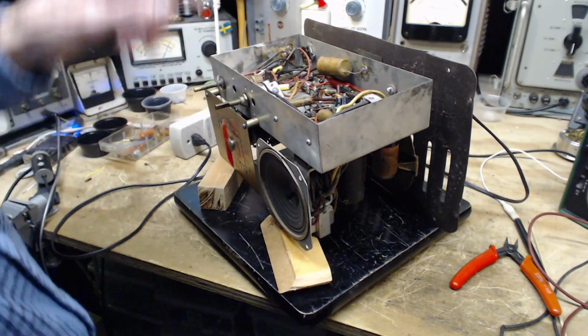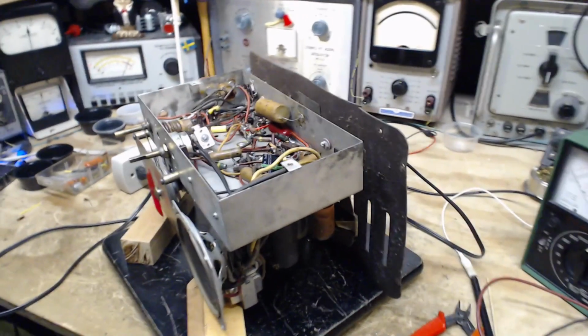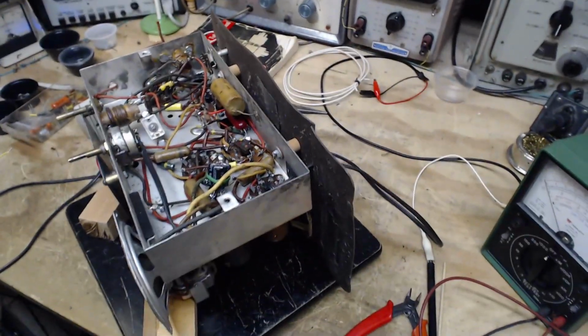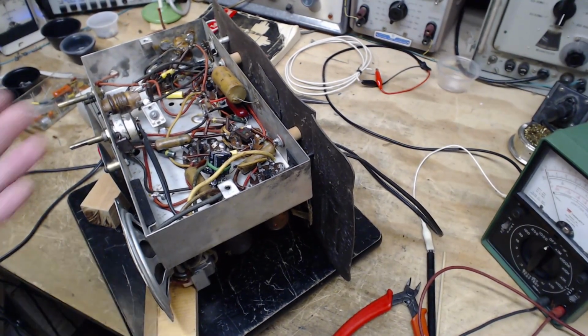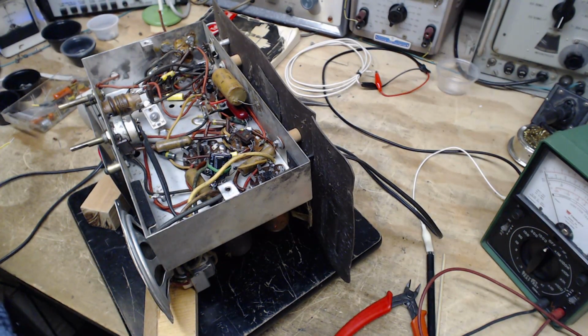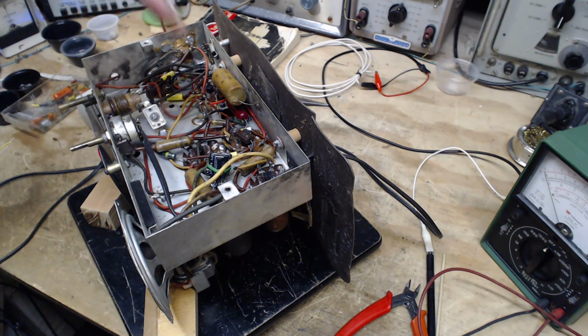Well, it strikes me that changing that capacitor has improved the reception of the radio, improved its performance significantly. I think I've gone from getting 1 station or 1.5 stations to getting 3 or 4 now, and this is just about as good as it gets in my shop here for a radio like this. So that actually turned out to be quite interesting and unexpected, and I think it has to do with what I was saying, that this capacitor's job may be more than one thing. It may be doing the AVC dampening and at the same time providing a ground to the antenna system, a signal ground back to B minus.